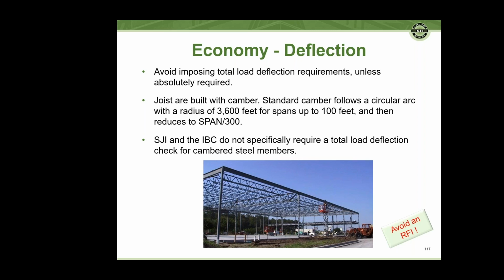The SJI and the International Building Code do not specifically require a total load deflection check for cambered steel members. So really there's no reason to specify a total load deflection requirement unless there's some very specific need that the camber will nominally offset dead load deflection.